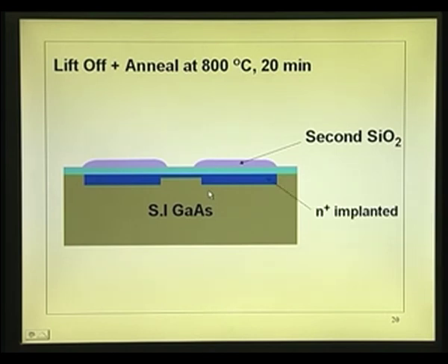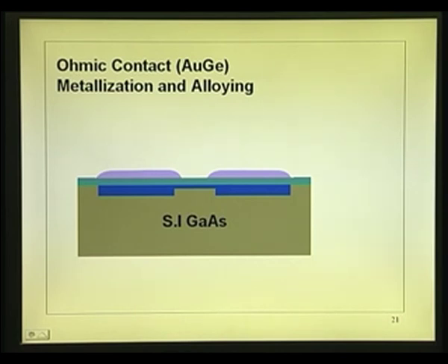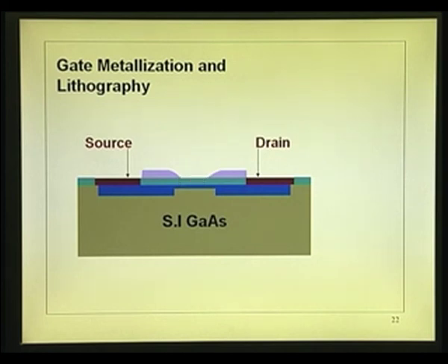That is all those numbers, the description. Okay. Make ohmic contact. You want to form the gate contact finally, without subjecting it to any heat treatment. So, make the ohmic contact. You can see the source drain contact is put there. Now, what you want to do is put a metal contact here. So, all these are by lithography. Source drain contact, gold germanium. Notice here, by lithography you can precisely etch this portion because there is no oxide there. It is a very thin layer, just about 1000 angstroms or less. So, you can etch it, even the dip etching will do, but you can put whole layer in photoresist, remove that portion. Now, you can do lift off technique again for realizing metal semiconductor contact only here.